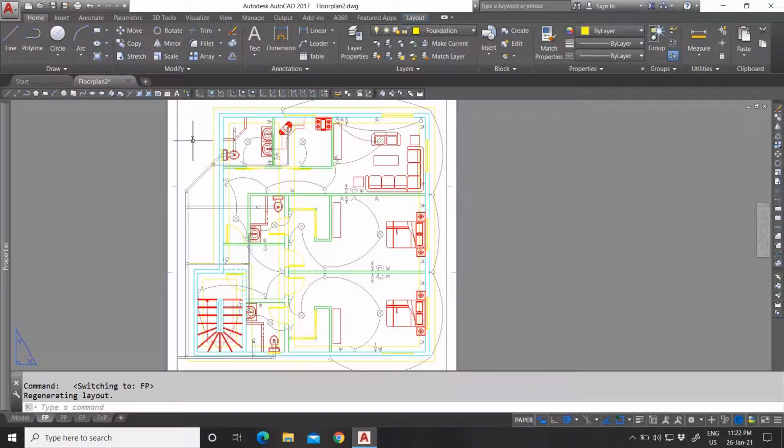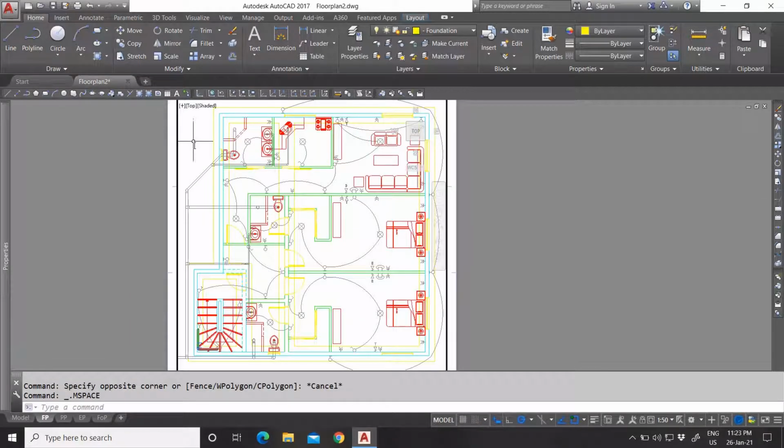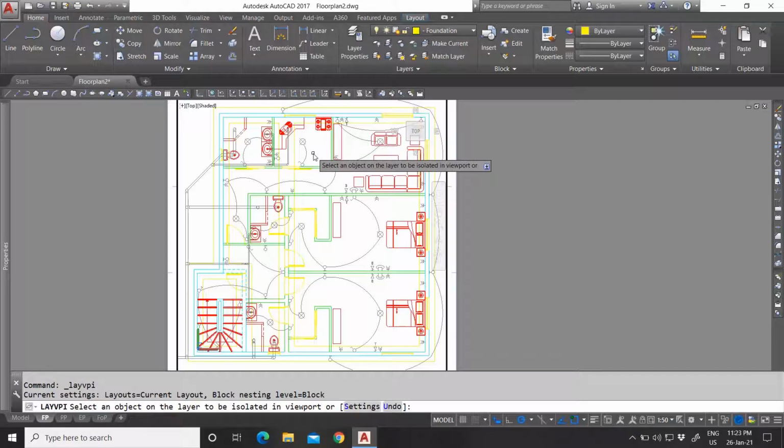They just want to see how the layout will be of the house that they are building. So then what you can do is just enter in this viewport and go into this button right here. So now you select which objects or layer objects you want to freeze in this specific viewport. Now I've selected that one.